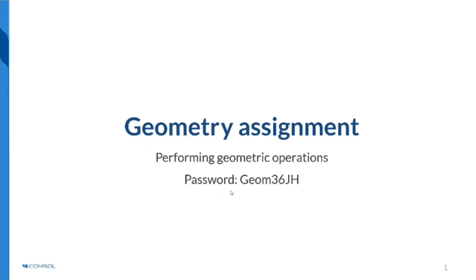Just one question, what is the need of using work plane? Well, if you are referring to the previous hands-on problem that we were creating, with work plane we could create that circular surface which is aligned exactly at the center of the center IC. Additionally, whenever you want to create any 2D object in the 3D work environment, you will need to use a work plane in order to create it, and that's why the work plane was used.